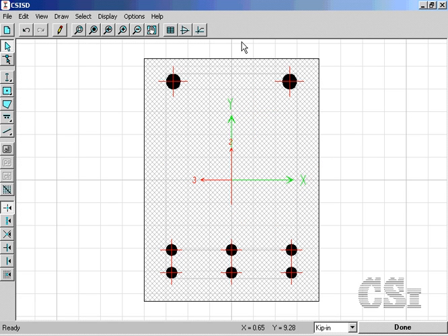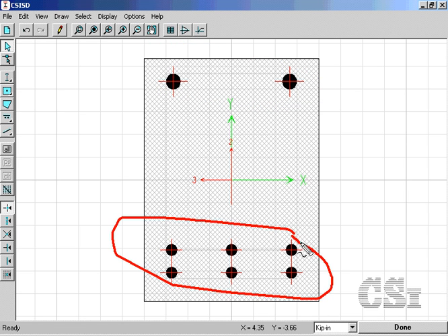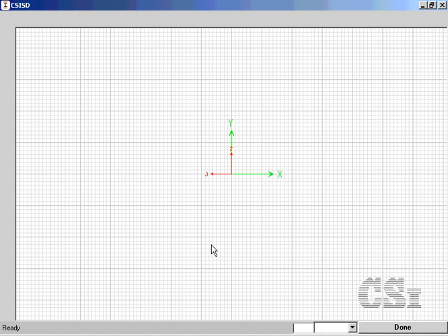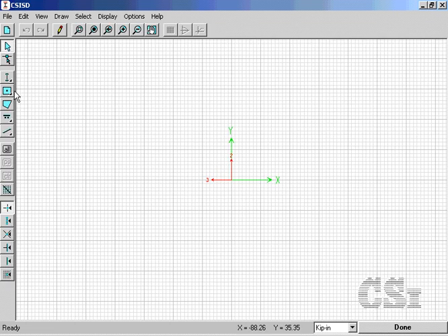For this example, we will create a rectangular beam section 12 inches wide by 16 inches deep. Reinforcing will be 2 number 8 bars at the top and 2 rows of 3 number 6 bars at the bottom. Cover will typically be 1.5 inches, except at the top where cover over the bars will be 1 inch. To draw the beam section, we will use the solid rectangle shape.